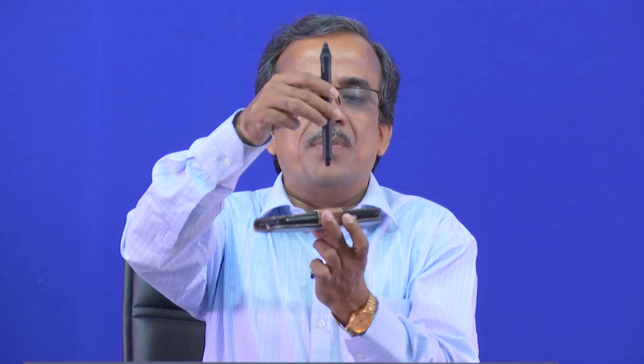Now, the moment I am considering this rolling movement, this type of rotation, this is the axis about which I am taking the rotation. So, this is nothing but x. The moment we consider this type of movement of the ship, that is called the pitching movement. So, this is the axis about which I am taking the rotation, and the moment we consider the yawing movement, as if this is the axis about which I am taking the rotation. Now, this concept of rolling, pitching and yawing has been copied in robotics.